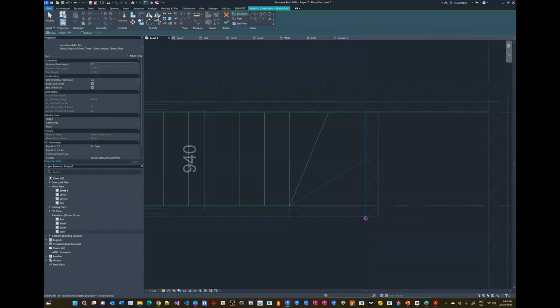I see we already have one. No, we don't. Okay, so we need a riser here at the end. We're going to draw that in. Sorry, that's not a riser. I used the wrong tool here. Make sure you select riser. You'll see that they change in color, so they need to be white. Let me create one there.